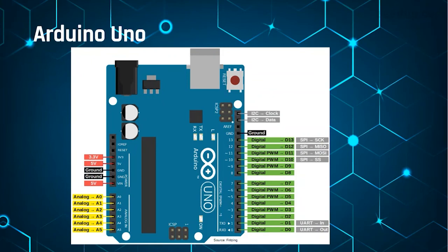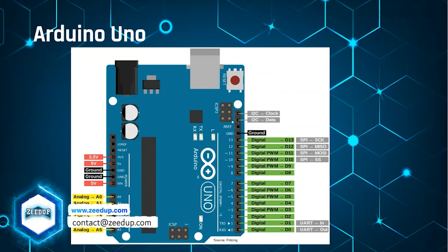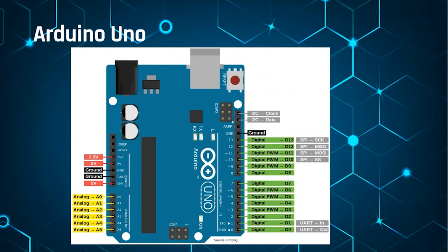Of course, if you have the power pins, you also need some ground pins to close the electric circuit. The Arduino Uno has in total 3 ground pins which are all connected internally. On the left side you can see the power pins and the analog pins available. It has 6 pins based on analog interface. On the right side you see the digital pins, ground pin and the RX-TX pins. We have seen their description above with the Arduino Nano. An extra feature in it is the power jack present in the top left side of this figure. So we can also provide power through this.